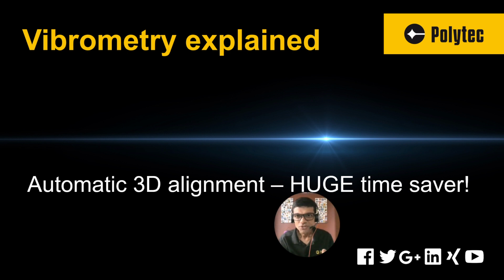As anybody who has used the 3D system knows, when you go through the steps, setting up the scan heads, doing the 2D alignment on the three heads, and doing the 3D alignment on the three heads, the 3D alignment takes the largest chunk of the total setup time. And it is the most critical step because it determines how well your laser beams overlap on the surface and the accuracy of positioning of these beams at the predefined scan points.